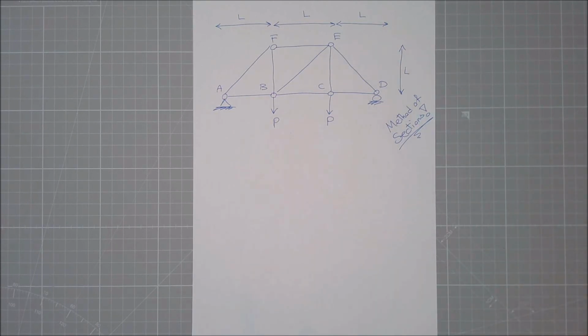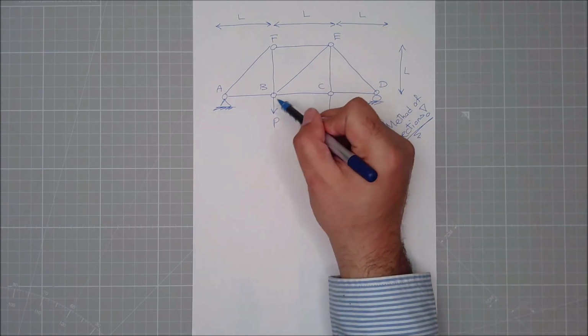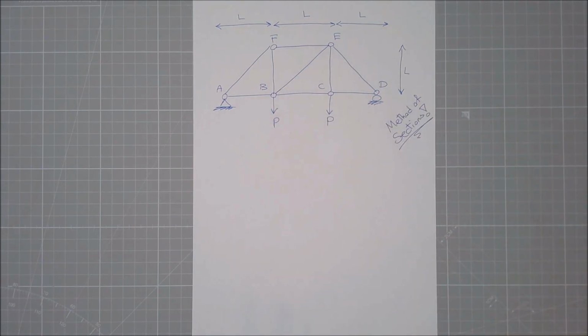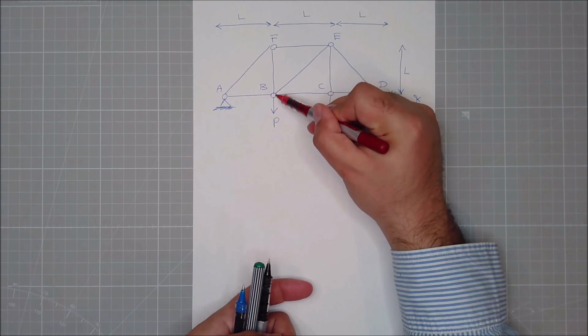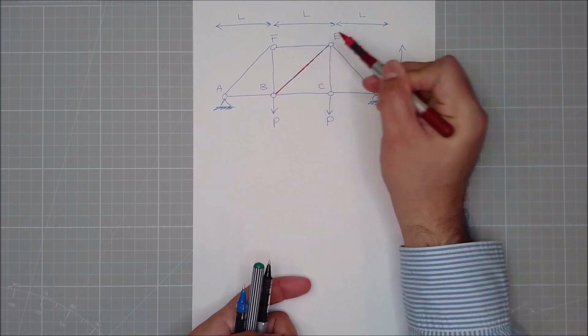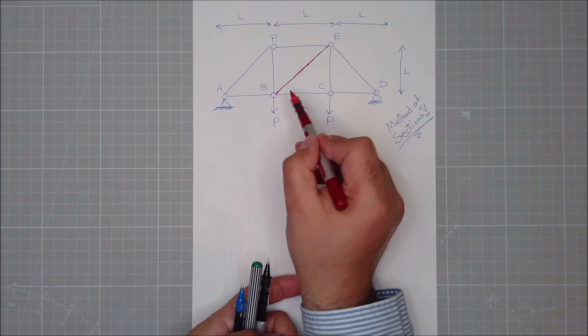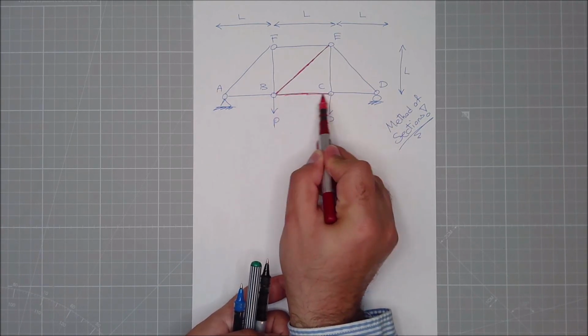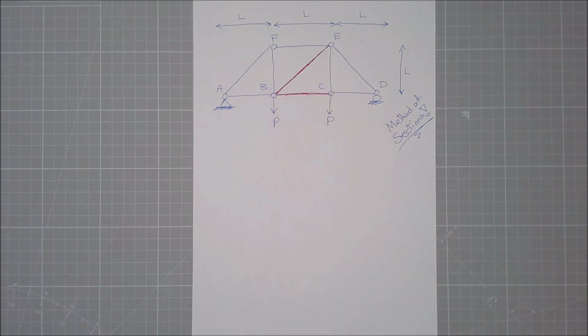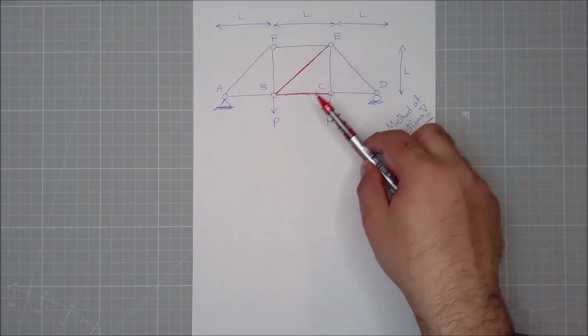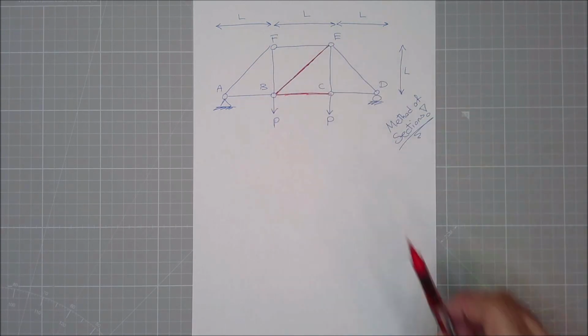So, method of sections. Method of sections is very similar to method of joints, but as we discuss it through the slides, it is perfect if you want the forces in a specific joint member or truss member. Imagine the question is asking us what are the forces inside the member EB and BC. So it doesn't care about the other ones. It says, okay, tell me what are these two and I will sort out the rest.